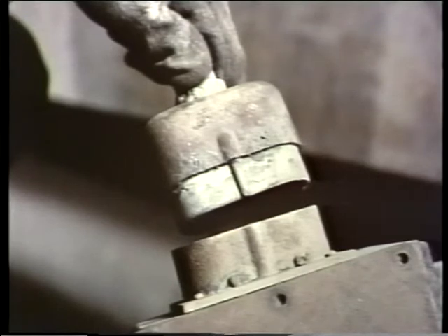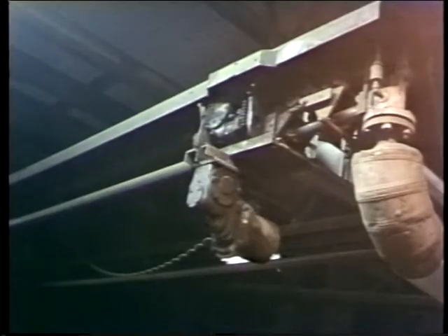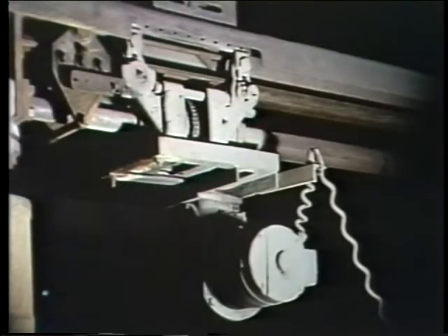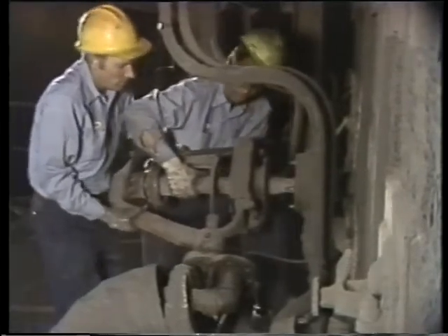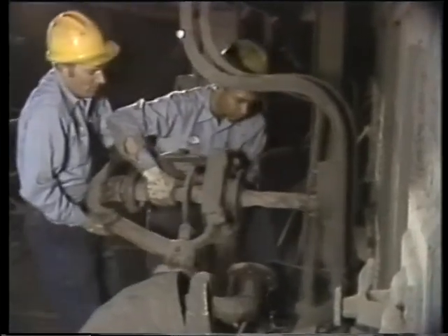Now, the soot blower in our example here has a special quick disconnect plug and socket for the electrical power to the drive. Some soot blowers, like this long tube retractable type, are hardwired. That is, the wiring from the power source is connected directly to the drive. That means you might have to count on one of the plant's electricians to disconnect the power for you. When everything is loosened, it's just a matter of horsing the thing around so the blower can be pulled away from the studs on its mounting.